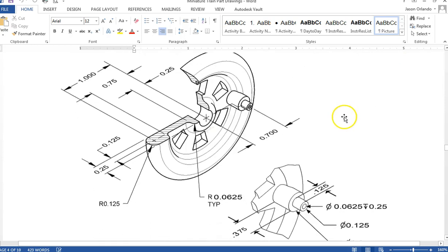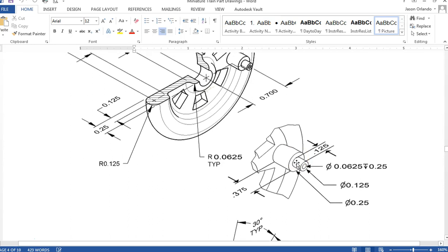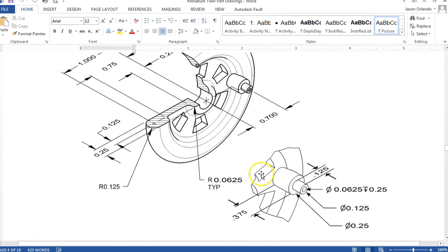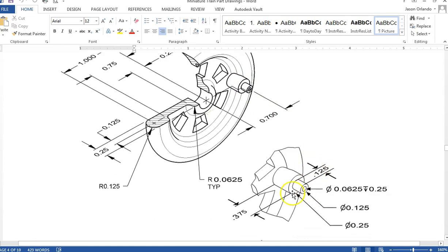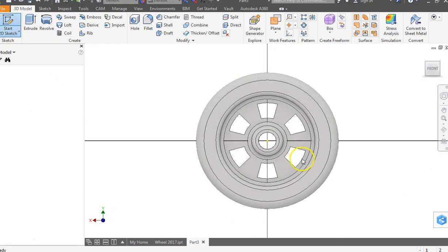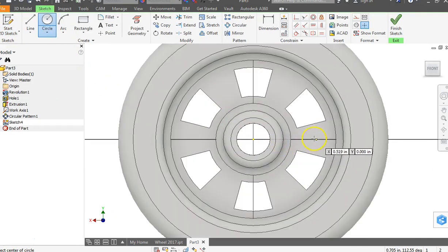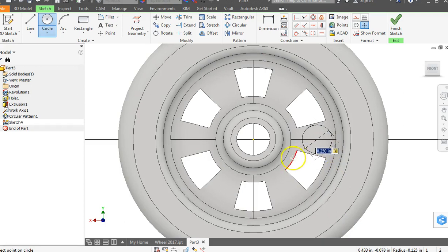We scroll back up. The last little piece is this, which is where the linkage arm connects. All right. Now the hard part is that if you look at the dimensions of where this center is right here from the center of the wheel, it's 7/10. And the size of it, let's see, here's a leader line here, is 1/4 inch. If you do that on the face, you're going to see that a circle that is 1/4 inch in, what is that, the radius or diameter? Yeah, 1/4 inch diameter.